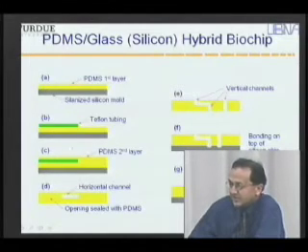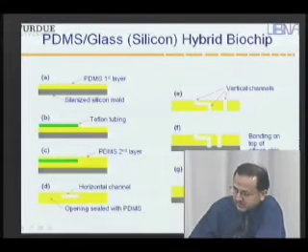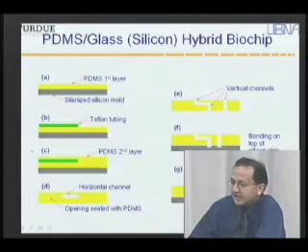You could then punch holes through these layers and form a vertical channel, and then attach this composite layer to another device that has a channel. And then you attach tubing to these channels, and now you have a microfluidic device that's a composite of PDMS and, let's say, glass or silicon.